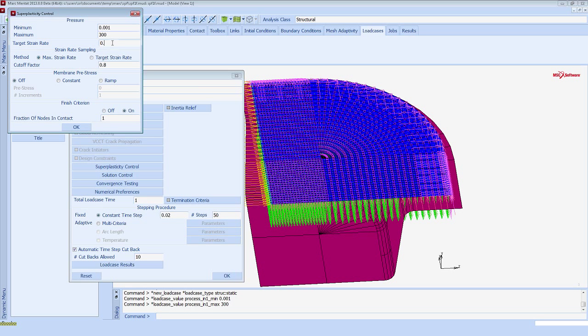And the superplasticity behavior itself exists only in a certain narrow range of strain rates. So we want to restrict to that range. Once again, that is a material property that you typically know. For this one, the value is 0.0002, and I entered it. So I want to maintain as close to that as possible as we apply the loads. So we don't want to apply loads such that the strain rate strays too far away from this number. And this one you can leave as default.